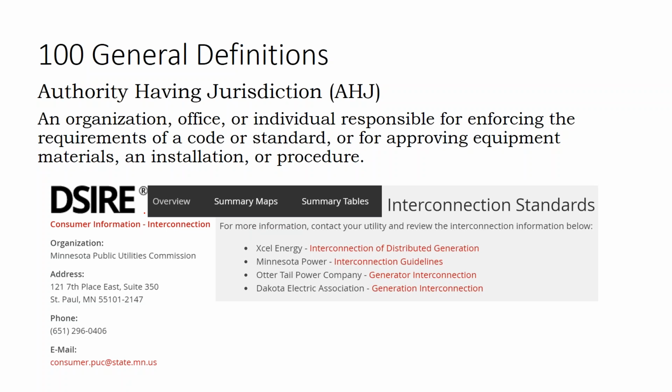But then again, there are minimums. A 100 amp electric service is the minimum service size. So even if you are trying to do a tiny house, and you might think, well, I'm going to force the customer to only live on 20 amps of power, there are minimum service requirements in code as well.